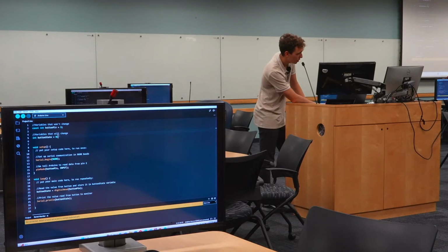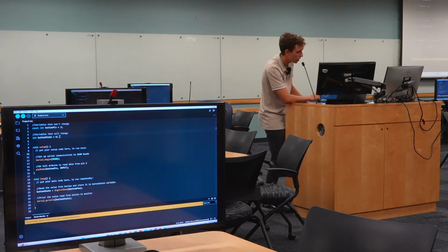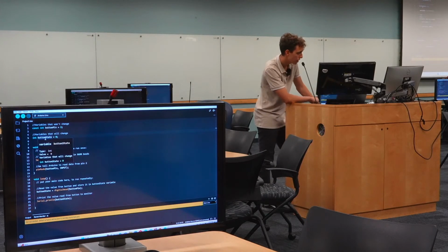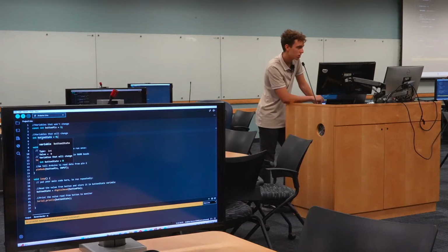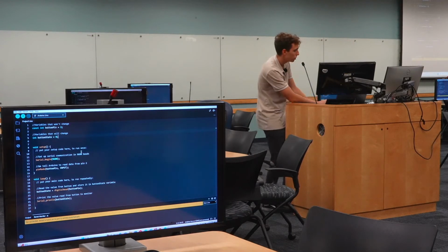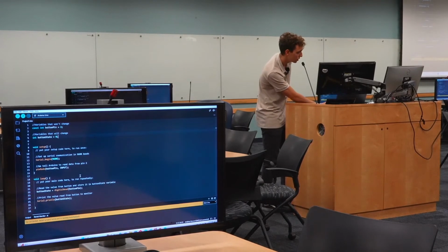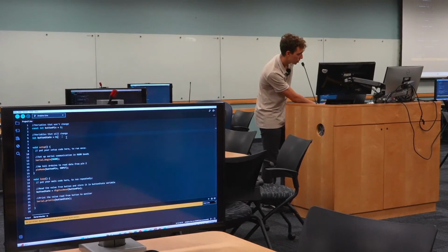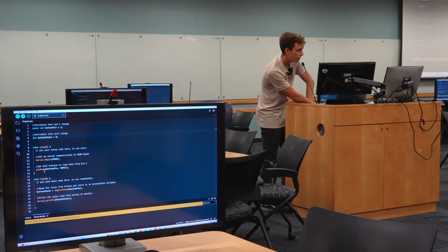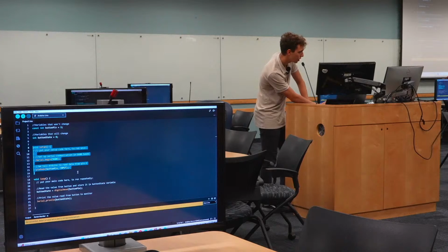And then we want to create a new variable, which is going to hold an integer again, which is the button state. This variable is going to change depending on the state of the button that we're going to read using the digital read. So that's on top of the sketch, always the variables. Then our second most important part is the void setup.